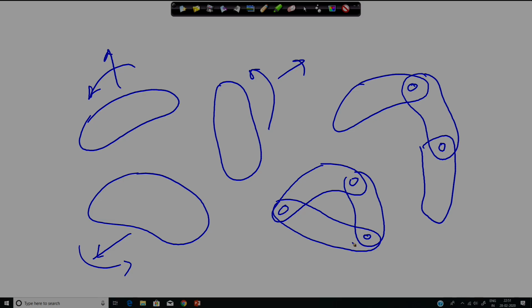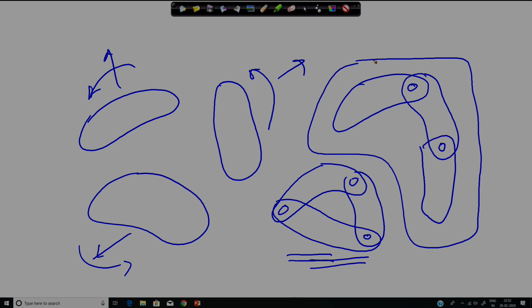This is what possibly you have in mind, this one, but then there is no relative motion, and it also does not satisfy the Kennedy-Aronhold theorem. You see the relative ICs are not on one line, so definitely this will have 0 degrees of freedom. But Kennedy-Aronhold theorem is not to be used in the inverse sense. So applying Kennedy-Aronhold theorem to this mechanism is applying it in a reverse sense, that if Kennedy-Aronhold theorem is not satisfied, they cannot be in relative motion. So, that is what this mechanism tells us. But otherwise, Kennedy-Aronhold theorem has to be applied when 3 bodies are in relative motion.